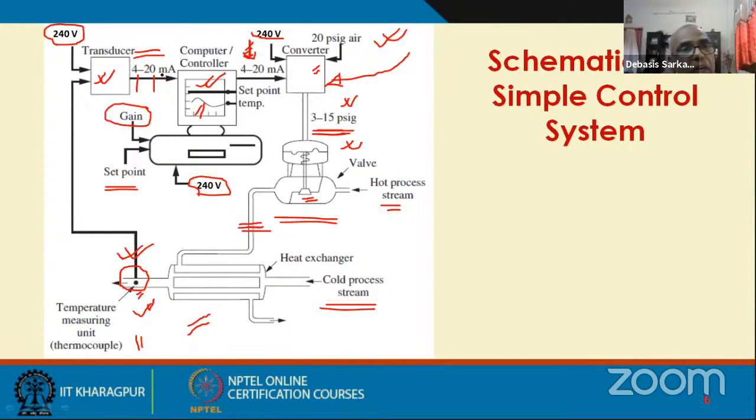Now, frequently, input at minimum level is 0. But we do not say 0 milliampere current as output signal corresponding to 0 input signal. Such non-zero output from the transducer for the minimum level of input helps us to differentiate between a faulty output or an actual output from the transducer corresponding to 0 input. So this is helpful in that sense.